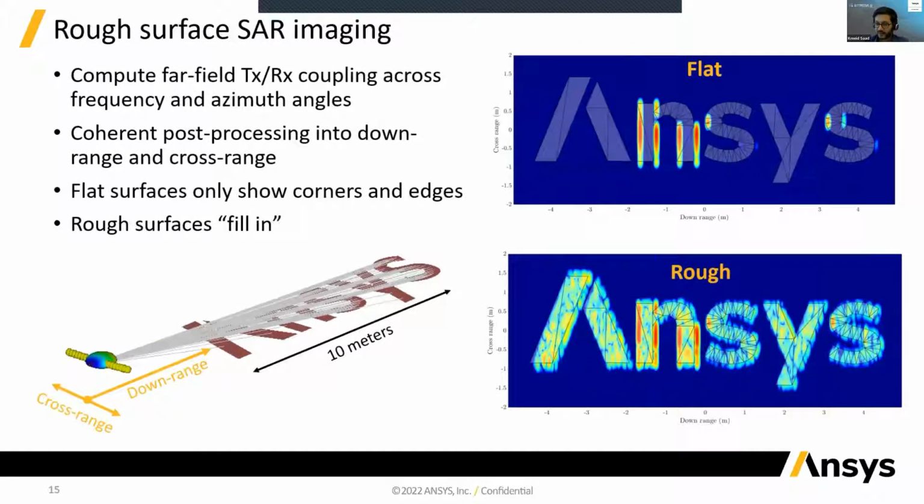Surface roughness, again, is also very important, considering that you don't only want to see specular reflections. Now with this new trend of 4D imaging radars, so radars that can also see in azimuth, so horizontal field of view more or less, and elevation, vertical field of view, I'm just making the analogy with cameras more or less, you need to see this azimuth spread and this elevation spread so that you can eventually create your 3D point cloud.